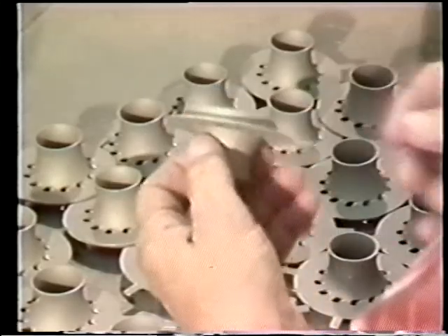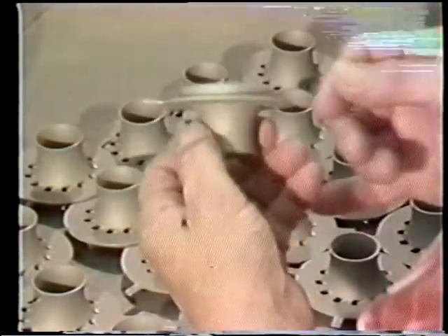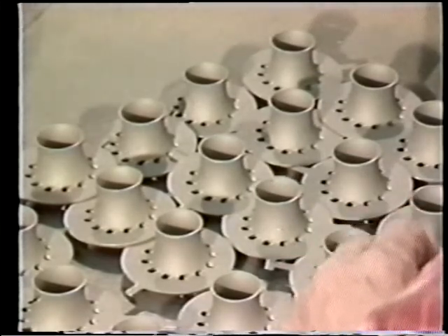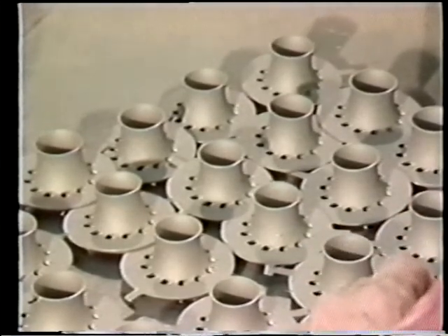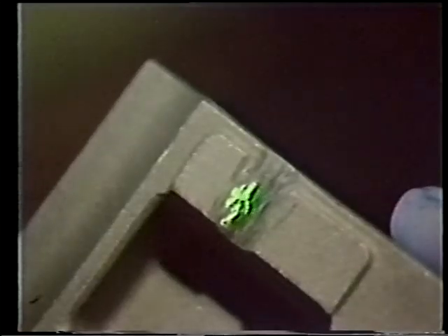Because casting involves melting and resolidifying metal, castings are subject to a number of defects which can affect the internal quality of a part. Shrinkage voids are holes produced in a casting as the result of contraction during solidification from the molten state. These voids may be small and uniformly dispersed through an area of a casting, or clustered into one or more large cavities within a casting.